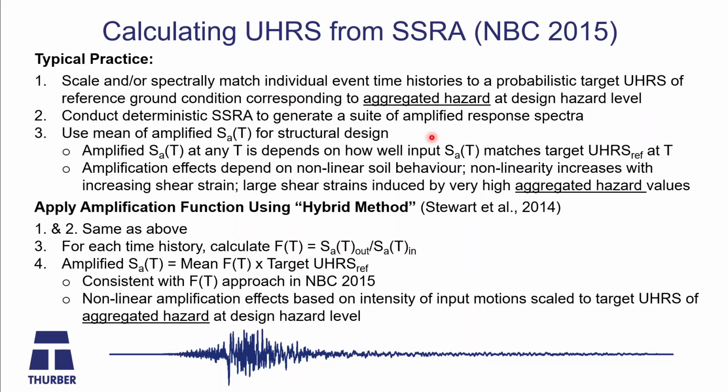the fact that we're using amplified response spectra is why we're wanting to do this thing that creates this beast that will never actually occur, because if you have a 2% probability of exceeding any particular hazard value, having an earthquake that has a 2% probability of exceeding all of those periods is pretty much like zero probability, right?